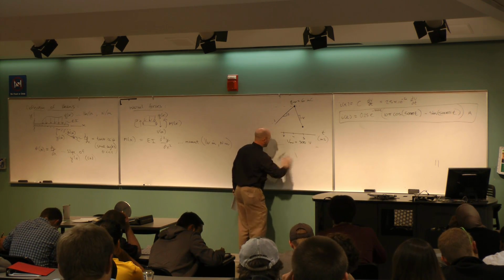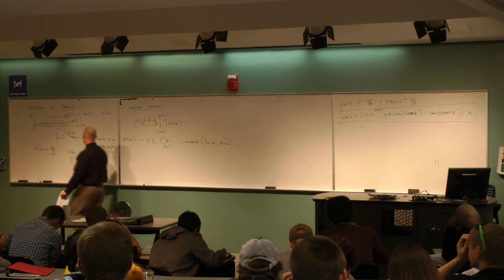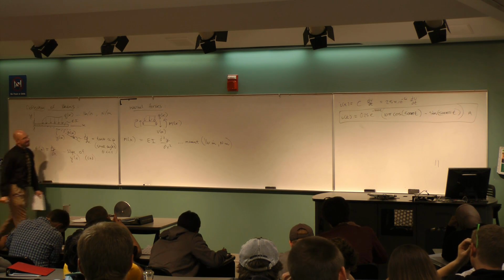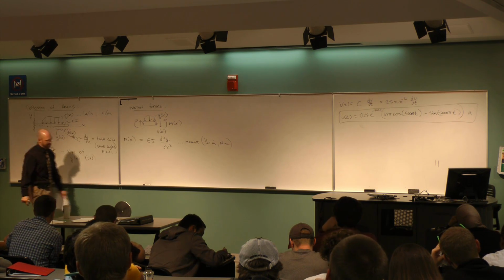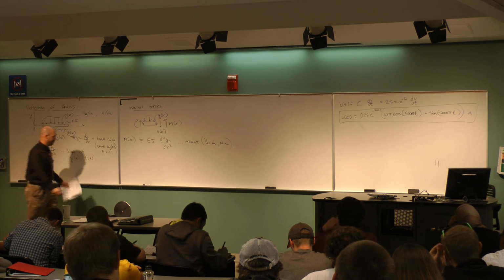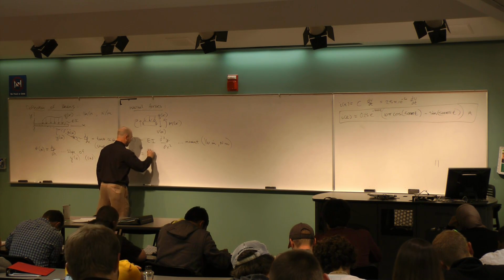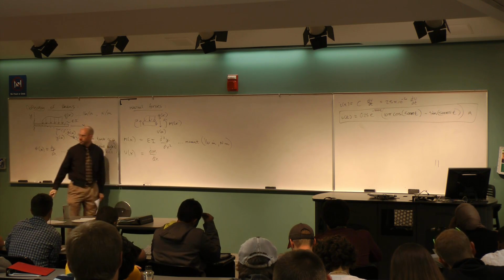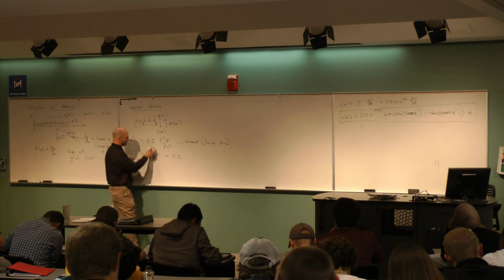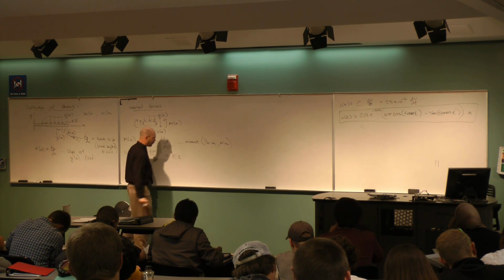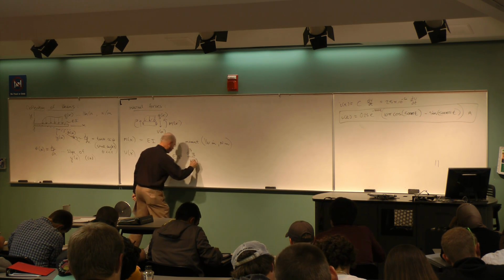So think about it. I started with y of x. If I take one derivative, I get the slope, dy dx. If I take the derivative again, and I multiply by a property of the beam, I get the internal moment in the beam. Well, it turns out that V of x is actually the derivative of the moment, dM dx. And if that's true, then the EI is still out front, because that's a constant property of the beam. And I have another derivative. So look at this one. 3 derivatives of y with respect to x.